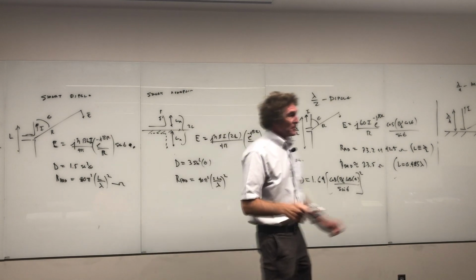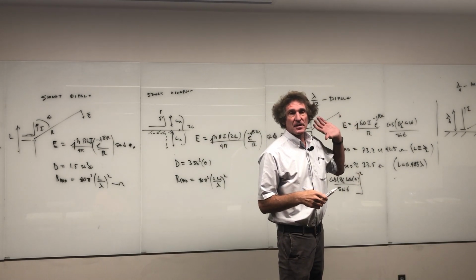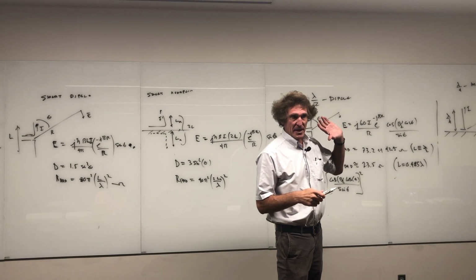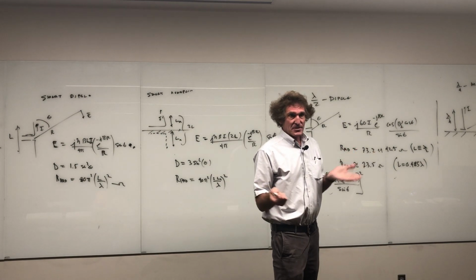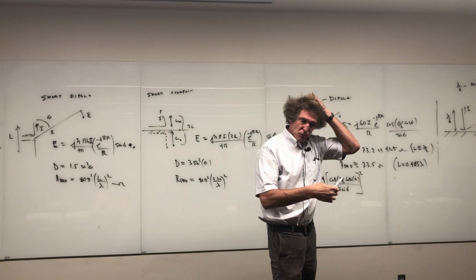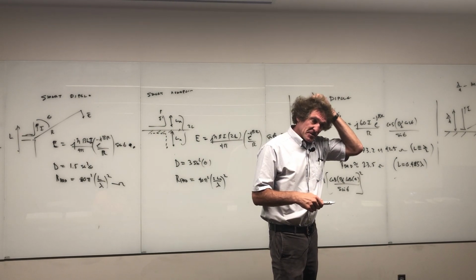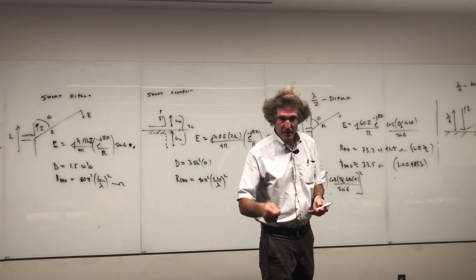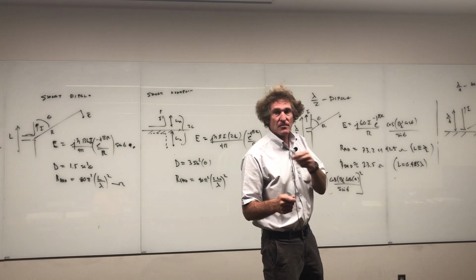I'm telling you this because if you work with radio power and large power, you always have to encounter these large capacitor banks. And most of the time, when I was where you were, nobody told me about this. So if I'm doing a project and need to discharge a capacitor, and I do the standard thing I did with labs, just short it out with a screwdriver or something, you do that over there, you'll kill yourself.